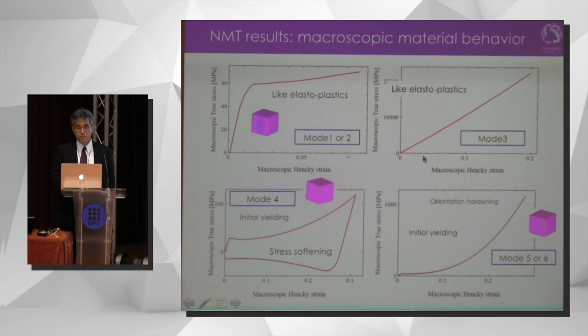This is the corresponding macroscopic material behavior. That is the stress strain curve. Then, as you can see, we have strong anisotropy, and also we have the viscoplastic and viscoelastic type model, which reflects the microscopic constitutive equation I have assumed for the unit cell.